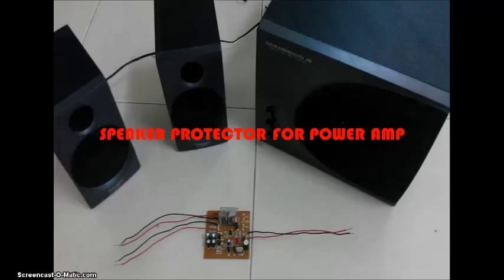The two main functions of this circuit are to protect the audio amplifier and the loudspeakers during the startup sequence, when the amplifier output might exhibit DC voltage, and also to protect the loudspeakers in the unlikely event of an amplifier power stage failure, where a DC component would damage the speaker voice coil.